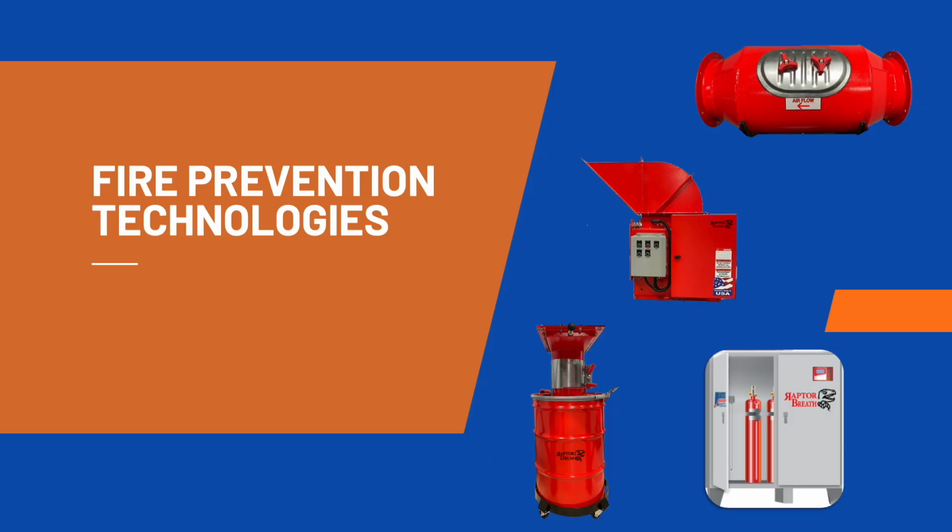We also offer explosion-proof drums, which protect and isolate the bottom of the hopper discharge from the dust collector or the vessel that you're trying to protect. Spark traps, which would be placed inside ductwork, and CO2 fire suppression systems, which we install inside of the collector or vessel that you're protecting. Basically it shoots CO2 and suffocates the fire. Next slide, please.